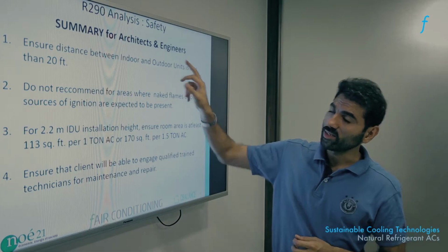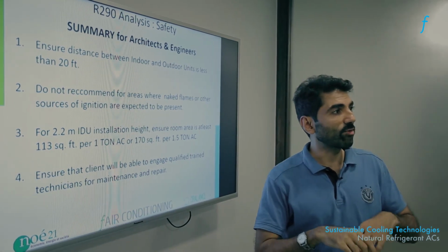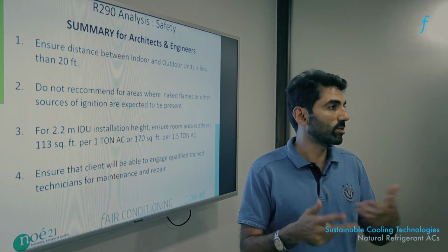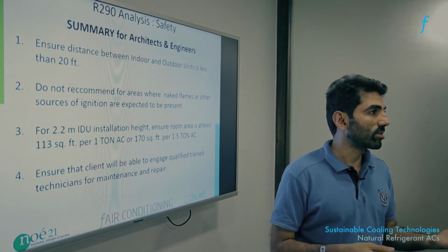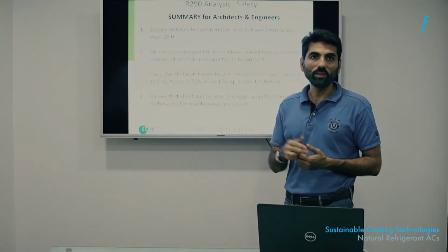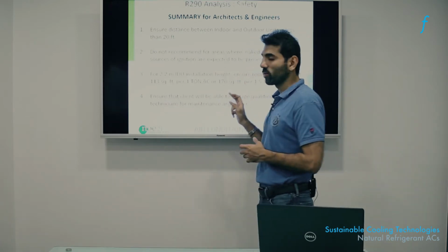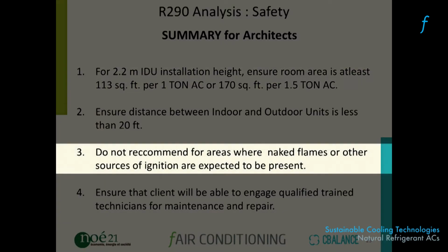Finally, this is a refrigerant that requires a lot of careful refilling and a lot of careful emptying out. For instance, the person who is filling or emptying out this refrigerant while maintaining it cannot have a source of ignition or a flame in their hand, for example, a cigarette or a beedi, etc. So this cannot be used in situations where the person who is the owner of this equipment is neglectful and does not care about safe maintenance of this AC. So we would not recommend people use this in applications where there's possibility of neglect of safety considerations.